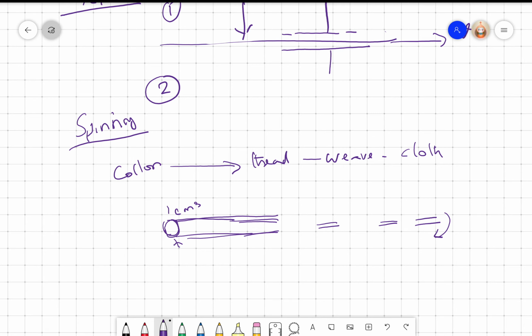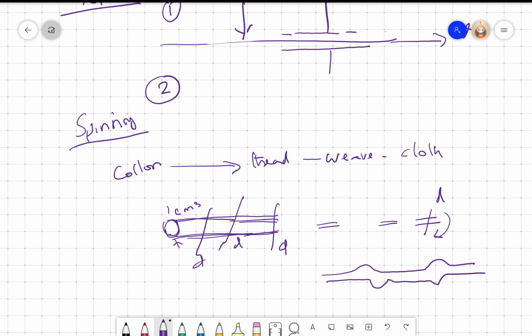So if and only if this preform is uniform, right? Wherever I check, I should get the same diameter, right? Then only I will get my thread also uniformly thin. Otherwise, the thread will be something like this, right? Somewhere it will be bulging and somewhere thin. This is not at all preferred. The value is very low if you don't have a good quality thread.